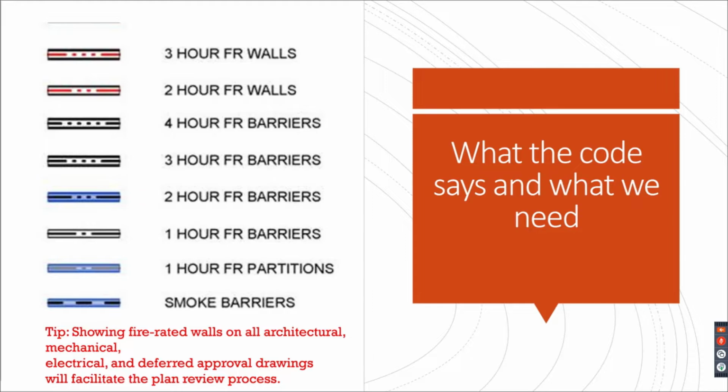So they built it as a 1 hour fire partition, and now this 1 hour fire partition surrounding this room that needed a 1 hour fire barrier did not have the proper door, the proper type of dampers, etc. So not something you want to see at construction, and certainly could have been resolved with having plans submitted with the proper information on it. So it seems very basic, but it's really, really important.